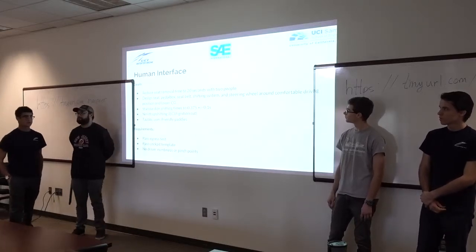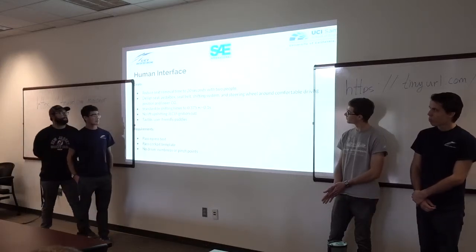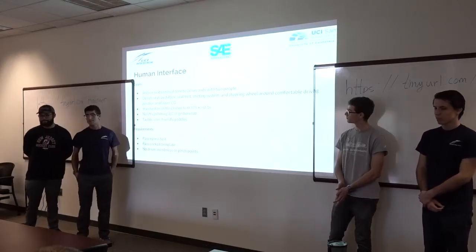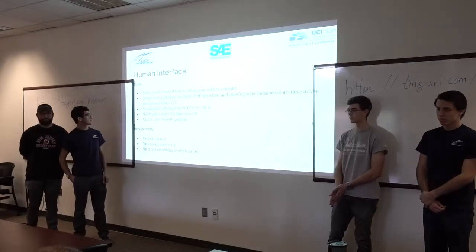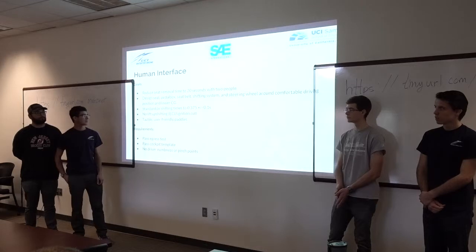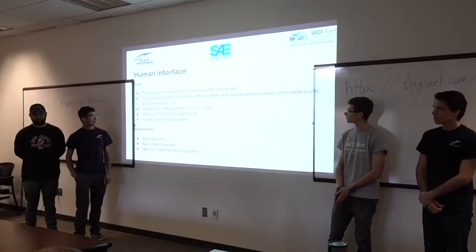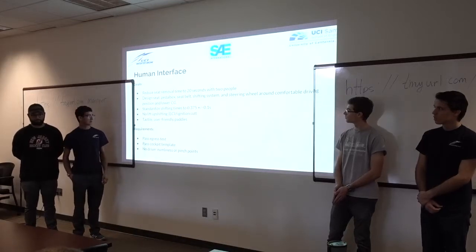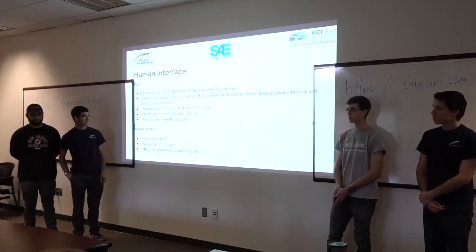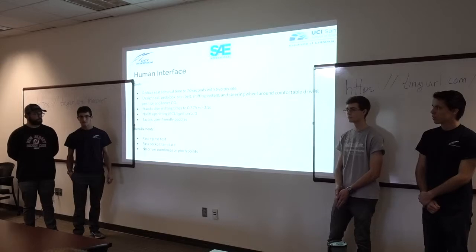So for human interface, the human interface lead, my name is Alec. We set the goals specified in the rules. We had the goals to reduce seat removal time to 20 seconds with 2 people. Design the seat, pedal, seat belt, and shifting system around a comfortable driving position and lower CG. Standardized shifting and over-the-top shifting and tactile, user-friendly pedals. These are the requirements specified in the rules.